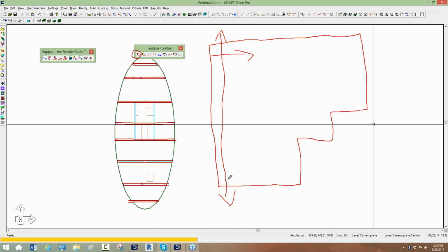And then we would map, if there's 1, 2, 3, 4, 5 points that define the high points and the anchor points of that tendon, we map those 5 points over some range that master tendon would apply and its shape. So in this case, the range, we would map it to point 1, 2, 3, 4, 5.